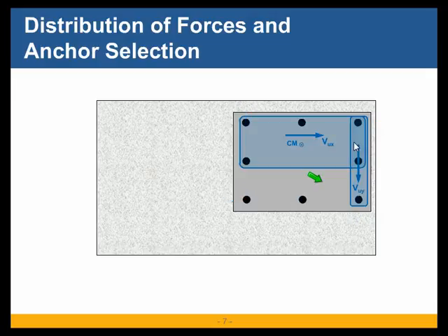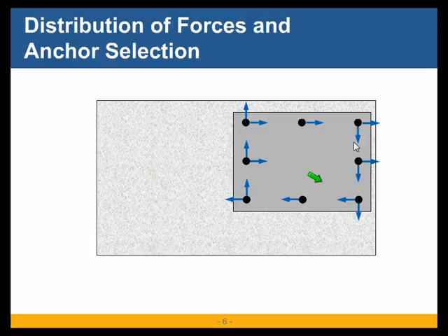So what Quick Anchor does, it would consider first the x shear, for shear in x direction, these 2 lines of anchors, these 2 rows of anchors, where the shear is acting in the x direction, and we know all those values, the individual values of those anchor shears, and then we can calculate